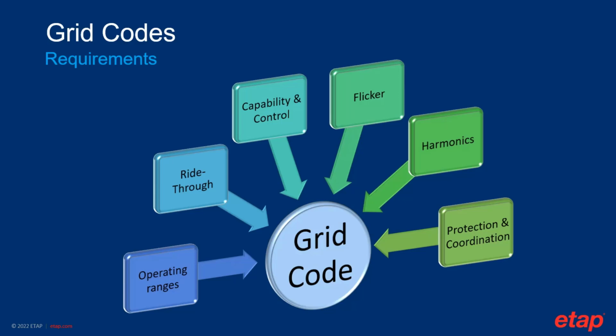In Europe, the European Network of Transmission System Operators for Electricity, known as ENTSO-E, define a common framework for the interconnected transmission system. The voltage at the point of interconnection and also the reference power of the power plant have an impact on the requirement. Usually, small generation units have few constraints, whereas larger ones must comply with much more challenging requirements.